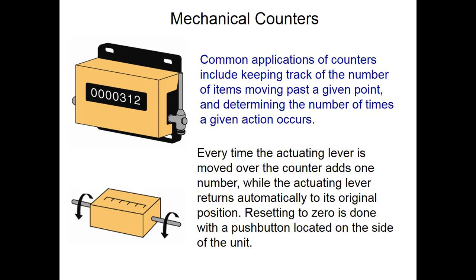Counters. So counters keep track of parts going past a given point. And so in the past, they've had maybe actuating levers or something like this that would advance a counter, or you would have solid state counters that you saw that would add one number. And so it's just count control. And now the PLC takes count control and it makes it a lot easier, very similar to timers. It's just an instruction set that you can add to your program. And then you can use different bits to figure out if a counter is done counting, or if it's in the middle of counting, or if the counter is enabled.